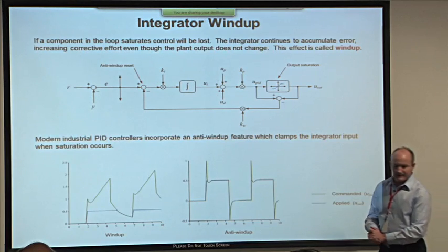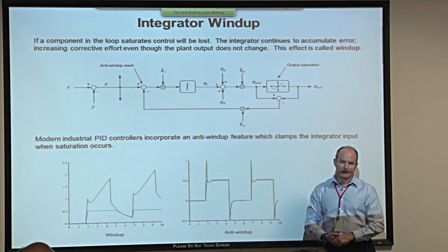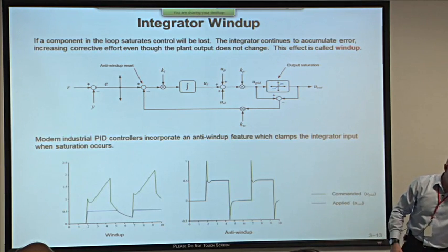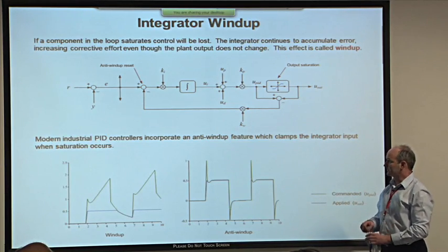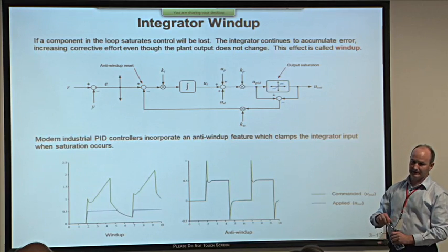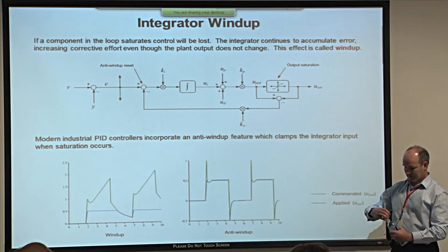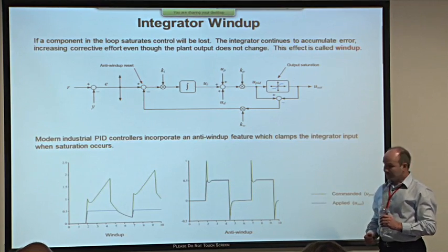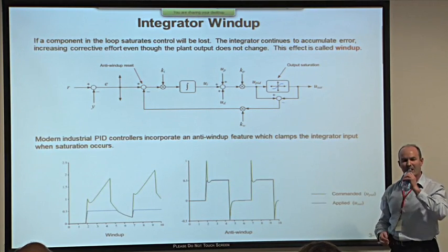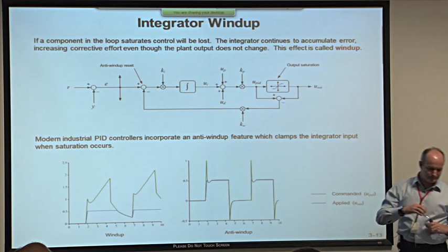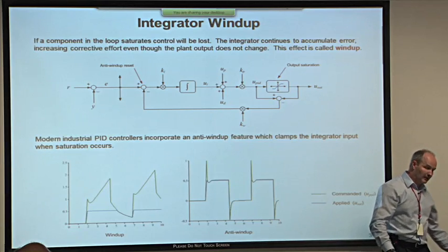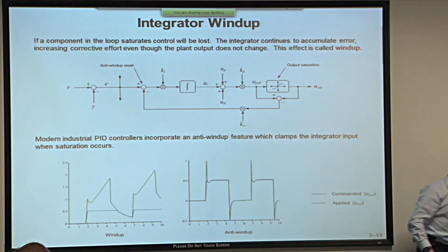All right. Now, I've dealt with rather ideal conditions here, and nobody who designs PID controllers for a living would design them quite the way that I've shown them here, or not more than once anyway. One of the things that integrators suffer from is known as wind-up. And wind-up occurs inside a control loop. Now, it's not terribly obvious until it happens to you, but once it's happened, it'll be obvious forevermore.